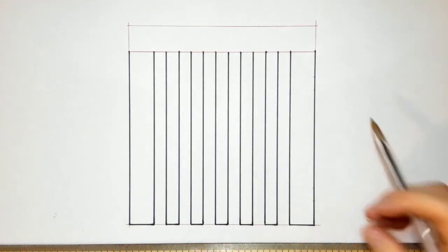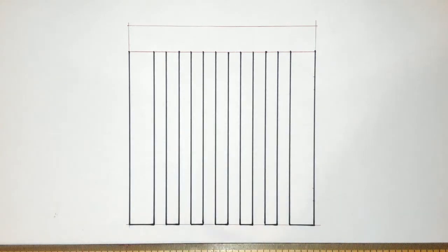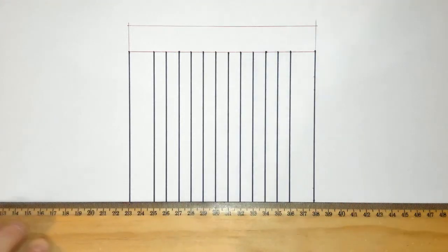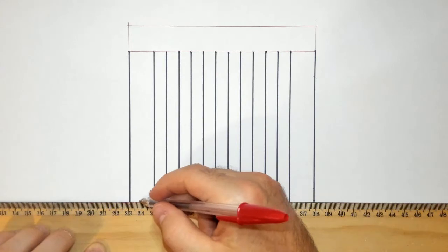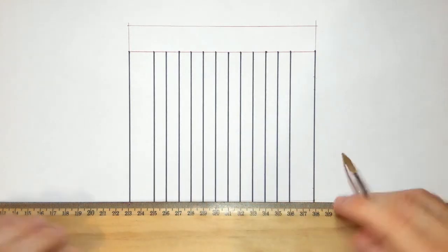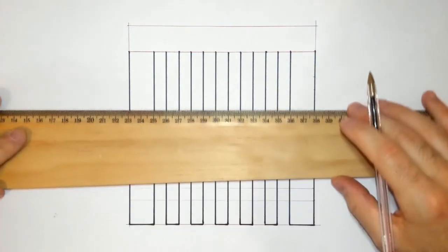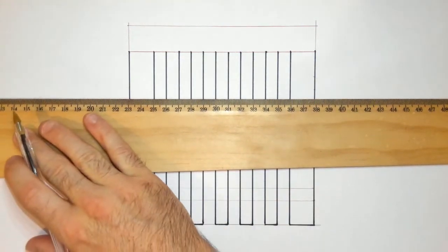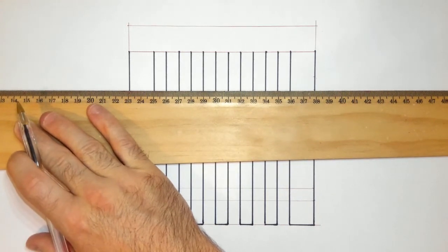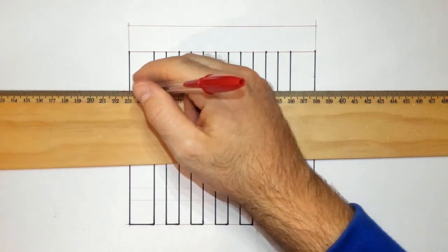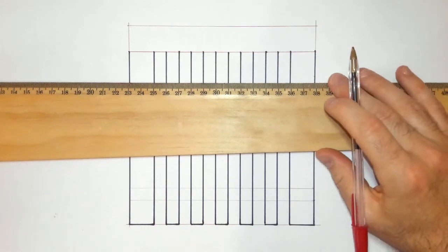Now I'm going to put in these little cross sections that have to go across here. Earlier on I measured up the heights. So this bit here is up 20 and then 10. The distance from here to the next one was 80 and then another 10. So I'm going to put in those cross sections. Remember, my red is my construction, so it doesn't matter. I'm going to do them straight across. I'm going to come along afterwards and mark in the heavy lines. So there's this one here and one final one.